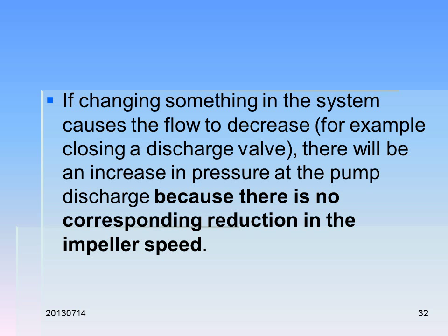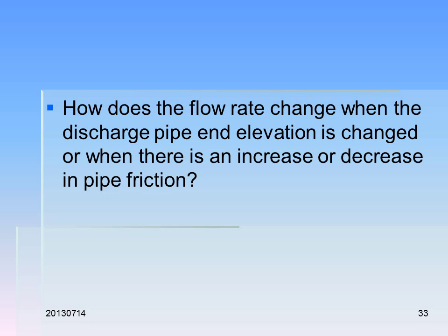So you have a decrease in the flow, but the pump is still running at the same speed, so you'll have an increase in pressure at the pump. It has to go somewhere. And it can't get out, so it's sitting there.